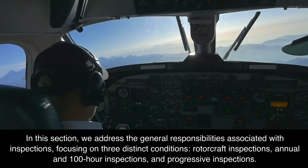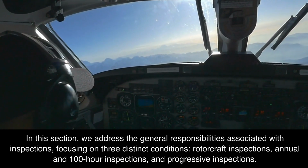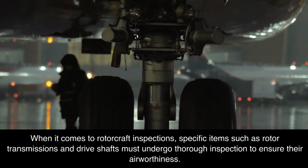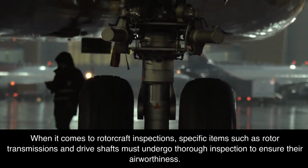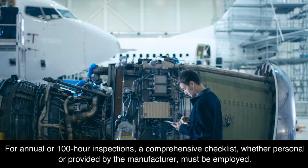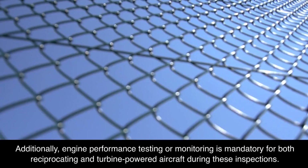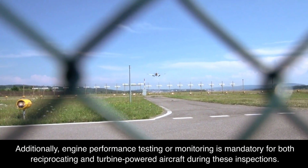In this section, we address the general responsibilities associated with inspections, focusing on three distinct conditions: rotorcraft inspections, annual and 100-hour inspections, and progressive inspections. When it comes to rotorcraft inspections, specific items such as rotor transmissions and drive shafts must undergo thorough inspection to ensure their airworthiness. For annual or 100-hour inspections, a comprehensive checklist, whether personal or provided by the manufacturer, must be employed. The checklist, detailed in Appendix D, outlines the scope of the inspection. Additionally, engine performance testing or monitoring is mandatory for both reciprocating and turbine-powered aircraft during these inspections.